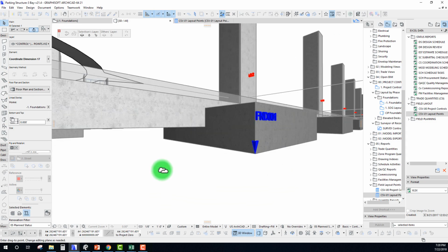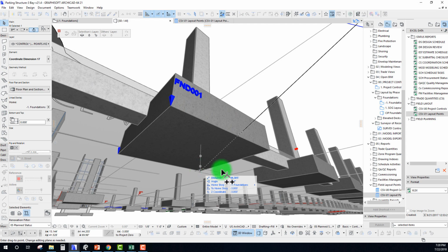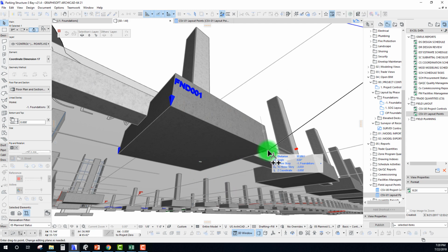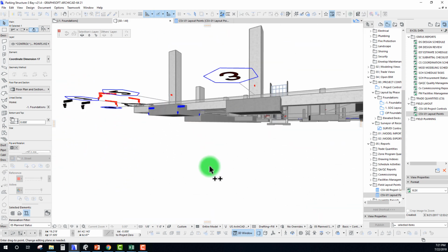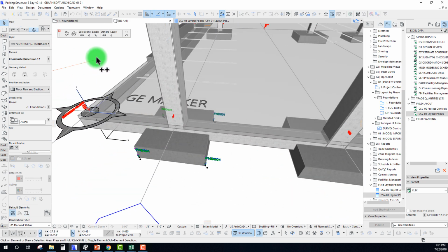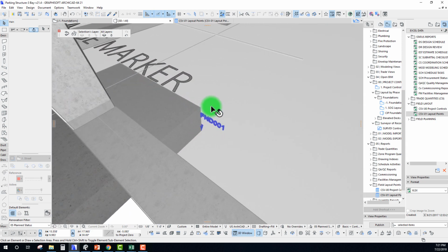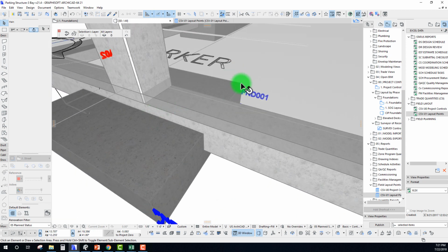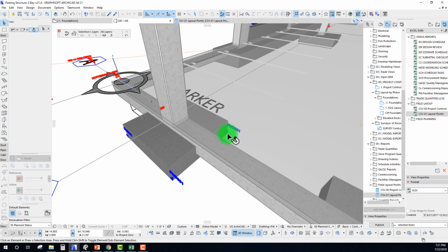So that's where we need to start, because that's the one that actually reads the values. And what I would do is come around and start snapping them in to each of the locations that we really need. And to do this, I actually like doing this in a wireframe, because the way ArchiCAD works with grabbing points, you can't necessarily grab that point through other elements. So if we had beams and slabs in our way, it actually wouldn't let us snap right to those points, specifically the lower ones here.